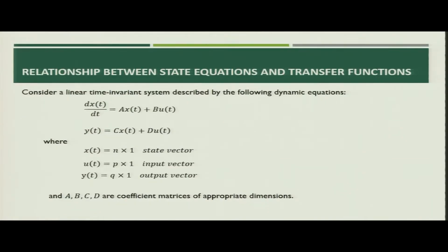Before going into the application of state variables in circuit analysis, first let us understand the relationship between state equations and transfer functions. We know that a linear time invariant system can be described by the following dynamic equations. The first one is the state equation, which we have seen in previous lectures: dx/dt = Ax + Bu.